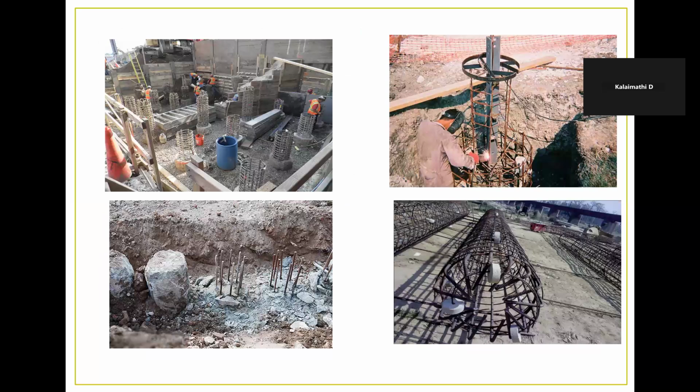Now, we are seeing about micropiles. Micropiles are quite popular in low-rise building construction. When the ground condition is weak and there is no adequate bearing capacity to carry the loads from the superstructure, a deep foundation needs to be constructed.